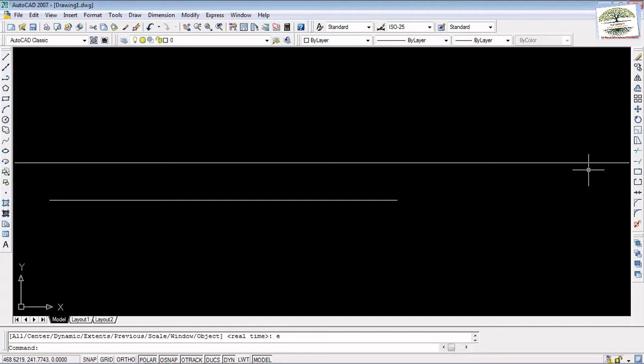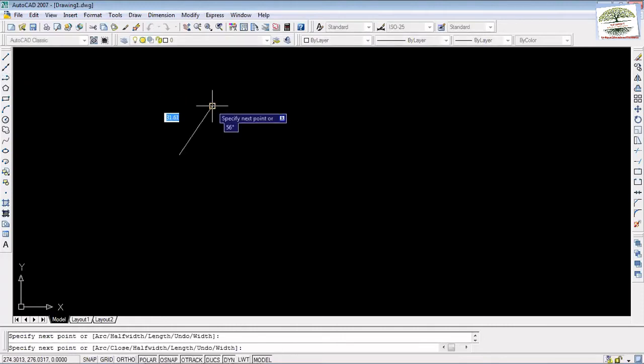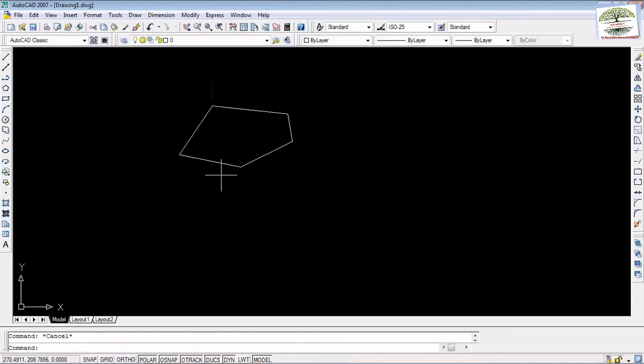Got my point? So Z itself is zoom, and E means extended version. So you're zooming to an extended version which is confined to the window boundary. That's it. Let's come to the third drawing tool, that is Polyline. See, this we have drawn. Click on it. See, this is actually a single unit. This is actually a single region, but you have drawn it with multiple lines.